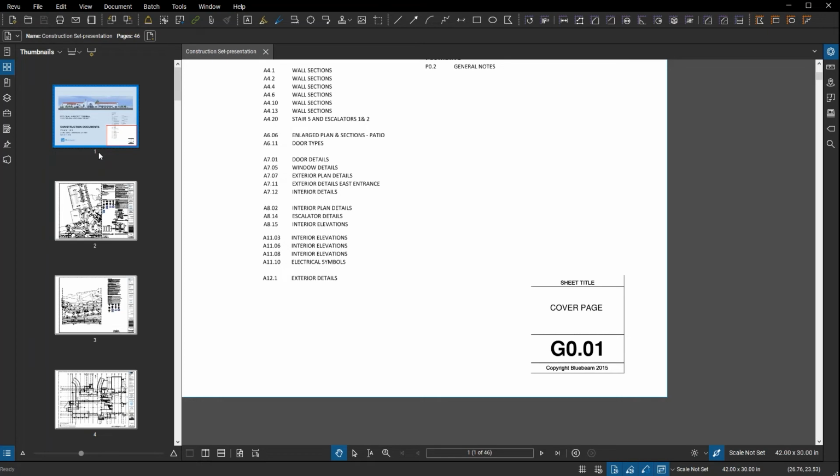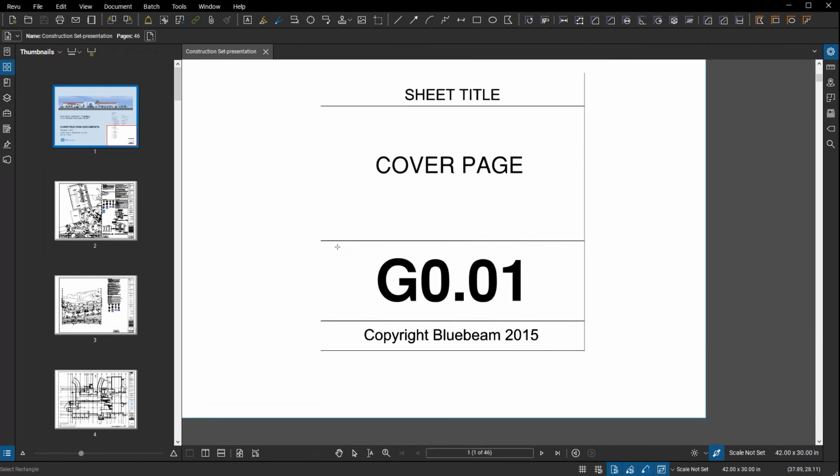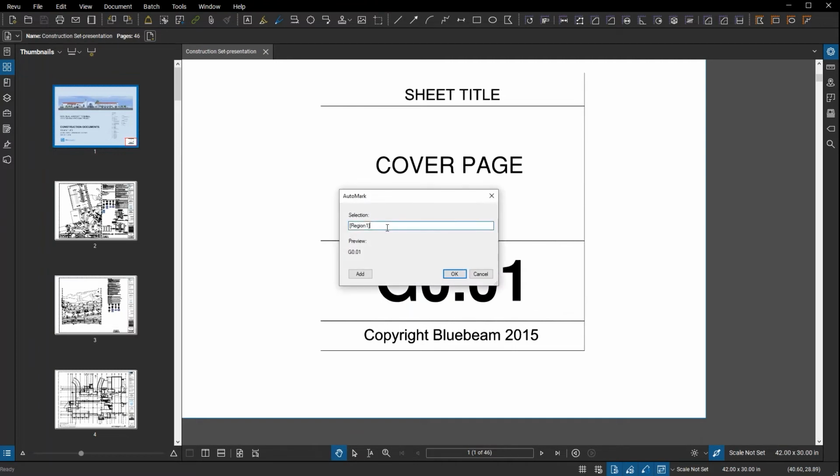Now, if you don't require it, you can go through and apply that within Bluebeam Revu, so the rest of the team that has to work on these files can do so a bit more efficiently. That's just a matter of creating your own page labels, and we can take it right from a portion of the PDF. Now, one caveat is that this does have to be a text-based PDF. If it's a literal napkin sketch that someone has just written on and drawn in some shape they want for a shed, you're not going to have this level of capability. But if a contractor, an architect, whomever has written this content, can supply a font-based, text-based PDF, this becomes an opportunity for you to take advantage of that data.